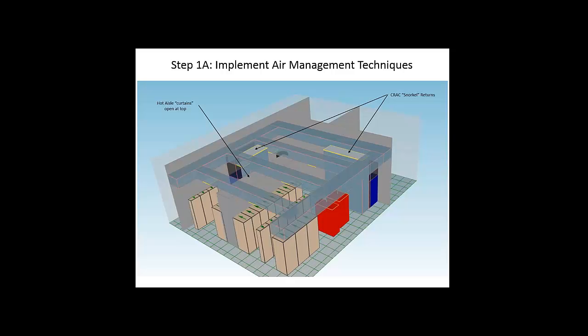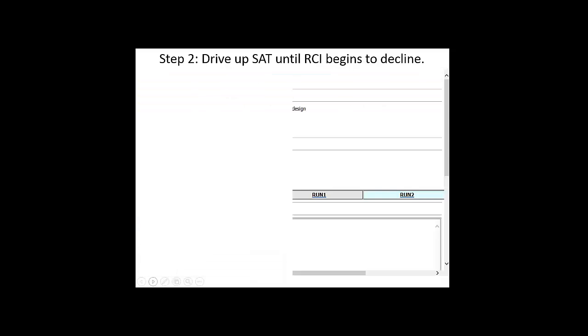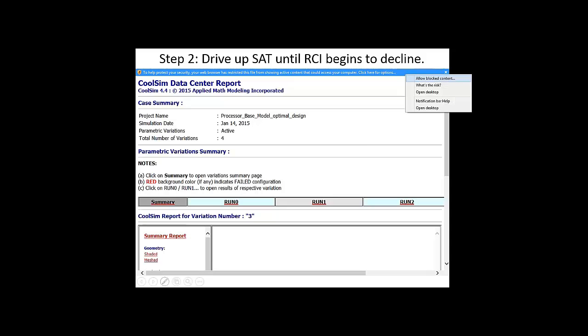The other thing I did is encase just one of the racks. This is a curtain. You can do these in many different ways. They do not have to be insulated. They don't have to be adiabatic at all. In fact, oftentimes curtains can work just fine. You do have to worry about fire codes a little bit when you do this, but it's a practice that is used quite a bit. So I put some curtains in place to force that air up into the upper end of the room there.